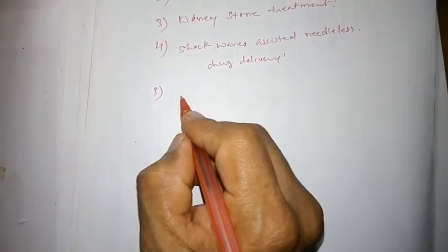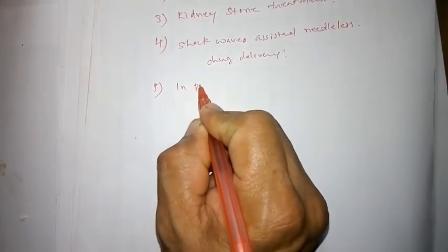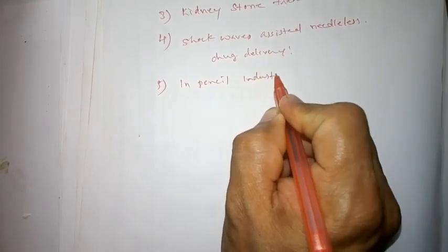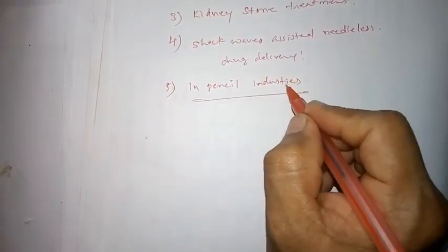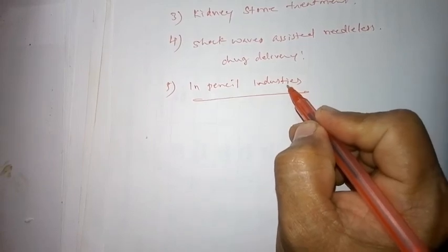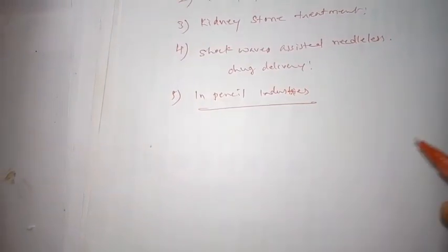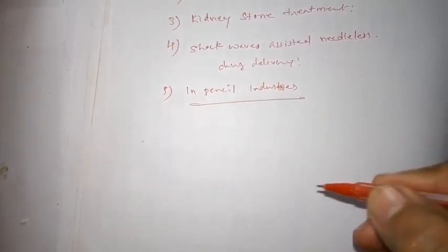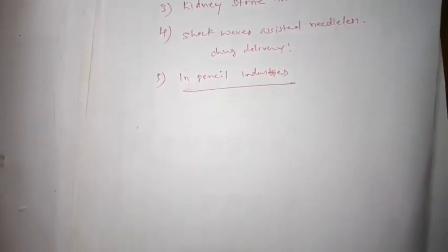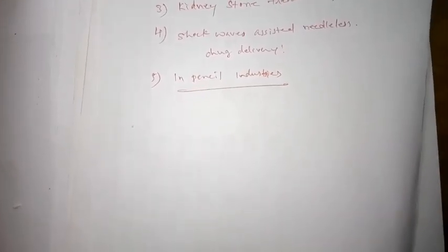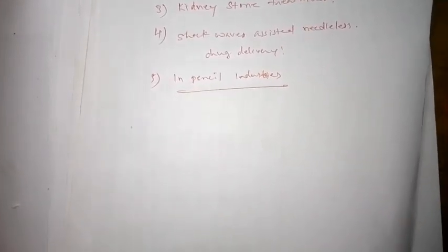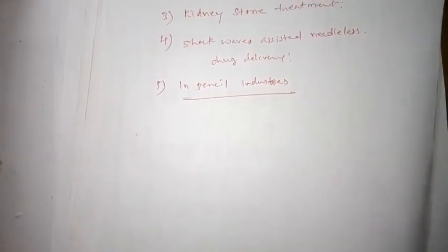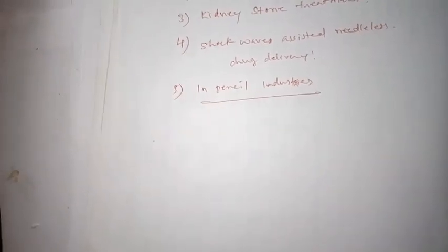Finally, one more application in the pencil industry. In the modern process using shockwave, wood is placed in a liquid and a shockwave is sent through. The liquid gets into the wood almost instantaneously. The wood is then taken out and requires no long drying time. So this is a very easy way to process the wood in the pencil industry.